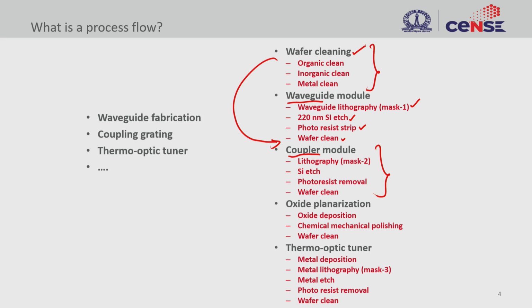And then we have planarization. We have discussed a lot about chemical mechanical polishing. So polishing is again a module. In this case, first you start with deposition. We have to do polishing in order to make the wafer flat, and then wafer cleaning as well. So everything is encompassed. A discrete module is a collection of complete unit steps in itself.